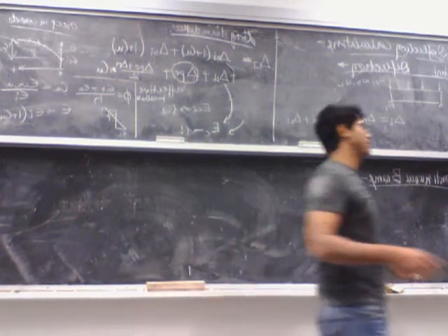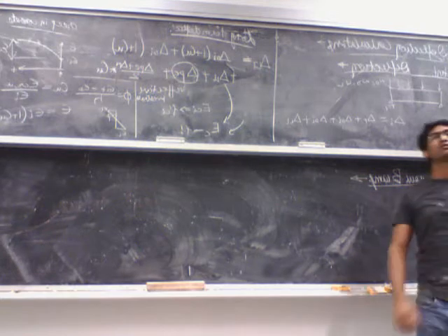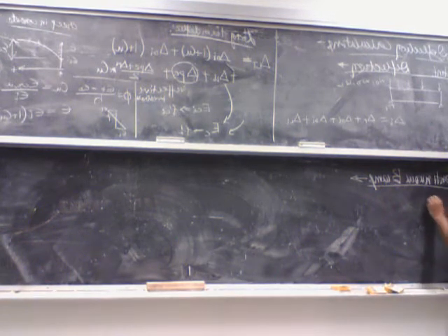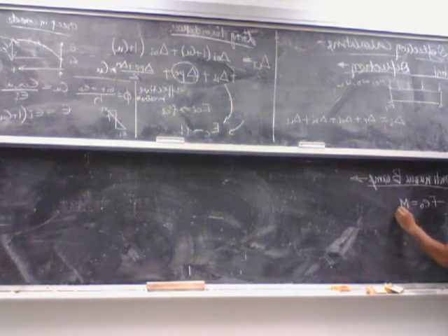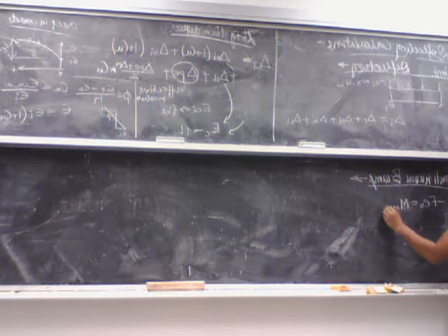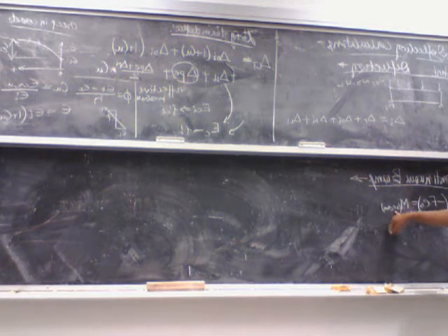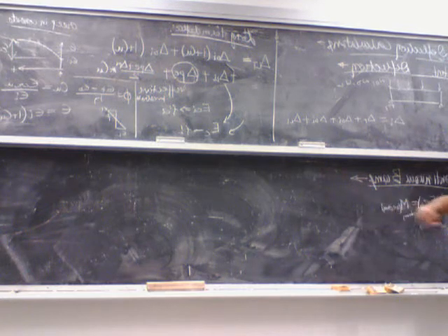In case of determinate beams, the good thing is if you are asked to do the load balancing method, you can simply say F times e naught or minus F times e naught is the moment at the cross section, and you could actually do the load balancing method to find out your F e naught and all those things.